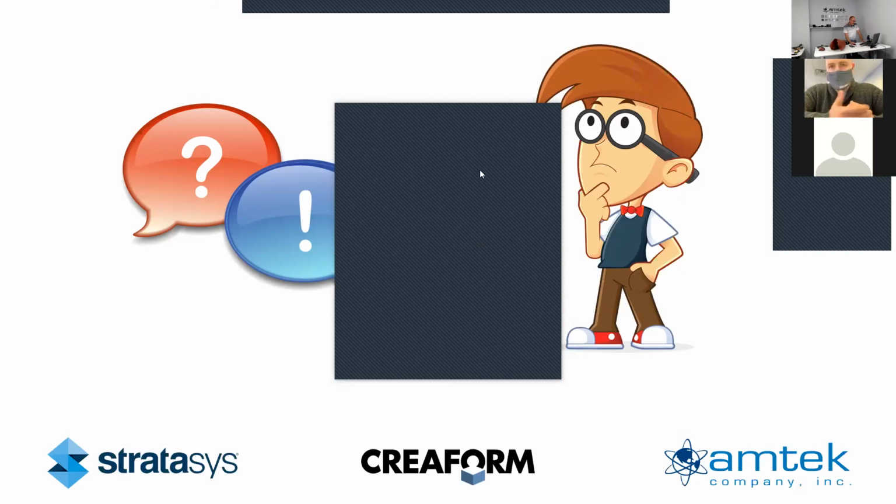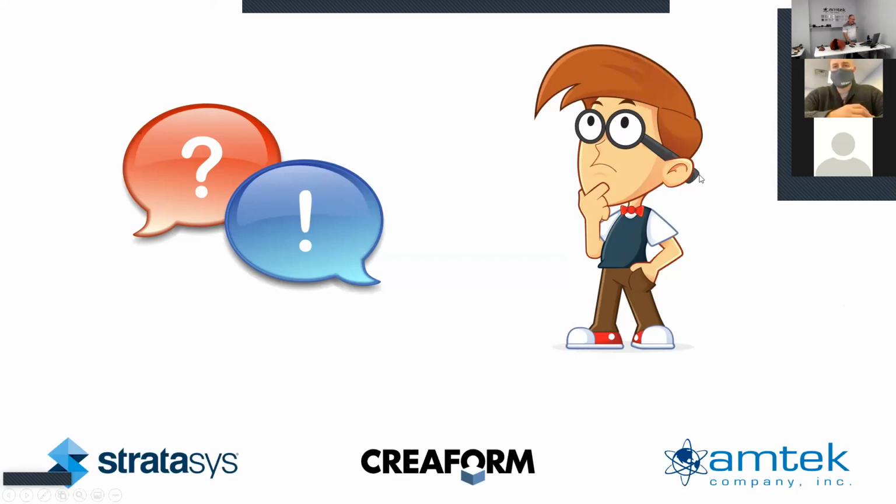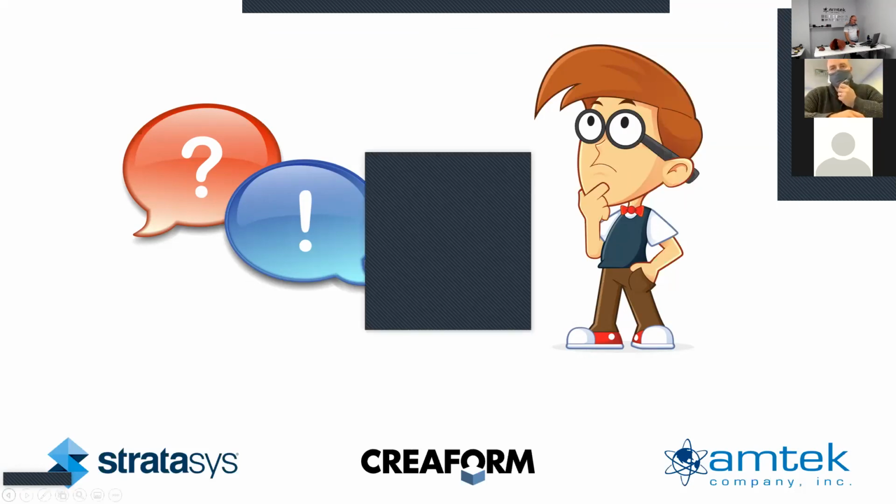And then I see Hector also asked about removing supports without a water jet. Yeah, absolutely you can. It makes it a little more laborious, but you can pick off anything you want when it comes to those PolyJet parts. Just an additional note to that: removing supports is about the only post-process that's actually required. So PolyJet isn't like SLA technology, where once the part is done, you have to put it in an additional chamber. The part's already cured and ready to go.